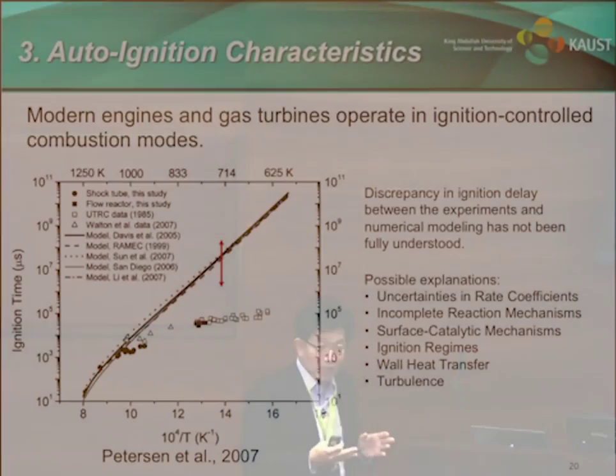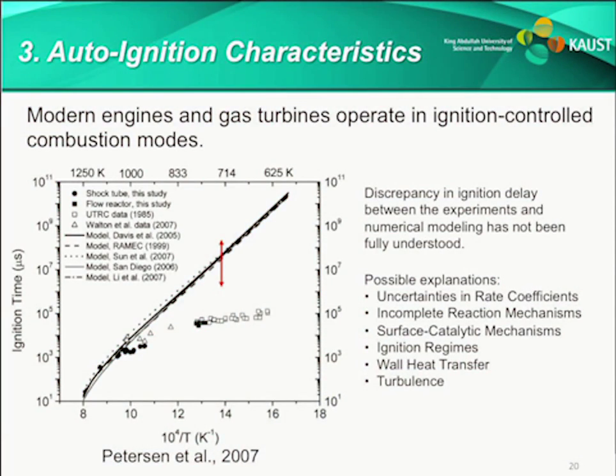And they're also talking about syngas-based driven gas turbine application. And the shock tube measurements, the RCM measurement ignition delay time was compared against the homogeneous Chemkin calculation as a function of temperature. They found a huge, like 2 orders of magnitude gap as the temperature goes down.